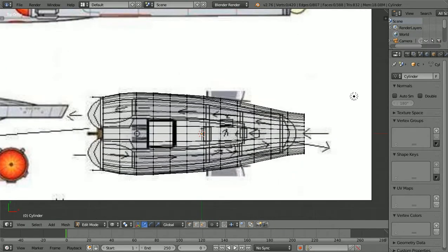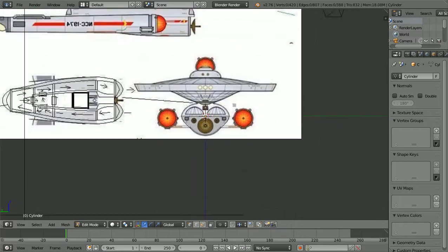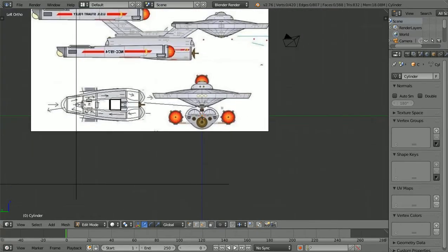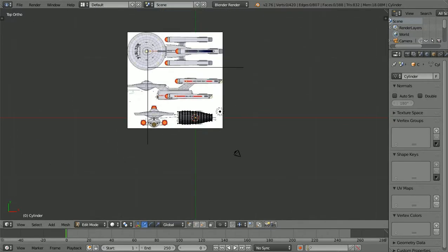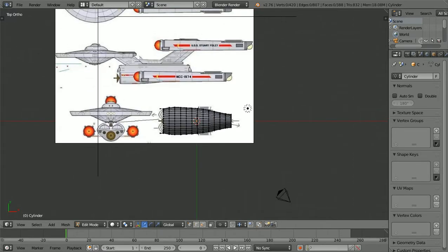So what I need to do is I'm going to hit Z. I could reverse all this, but I'm not going to worry about reversing all this. I'm going to hit Z, and I'm going to hit Control 3. I actually push the Control, then the 3 on the number pad. When I use numbers, I'm usually talking about the number pad. Now the problem with that is that now the picture's in the way, so let's hit 7. Let's go to Object Mode. Let's deselect this. Let's grab this picture.